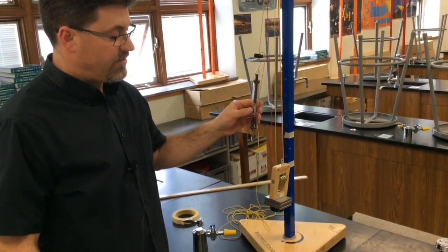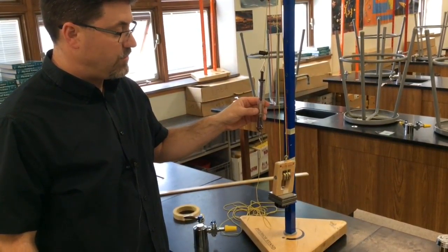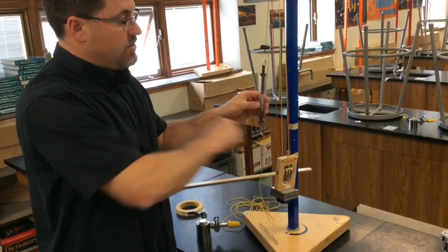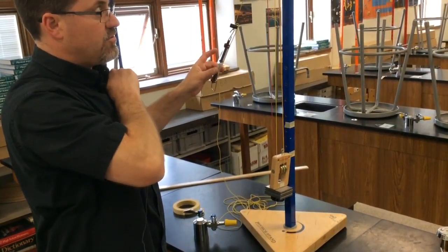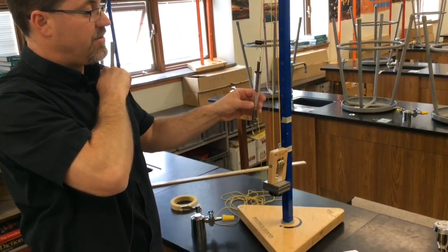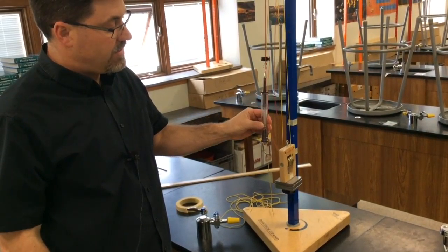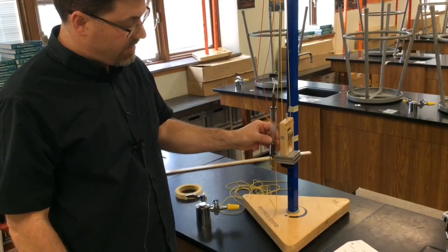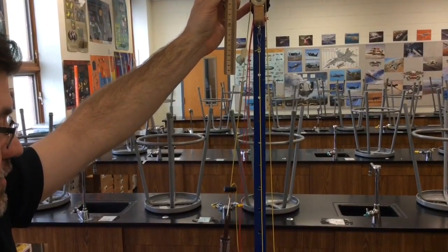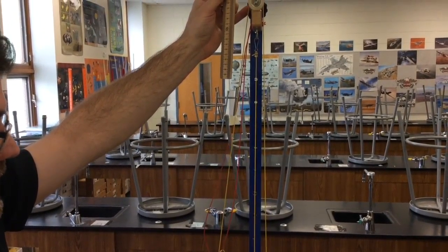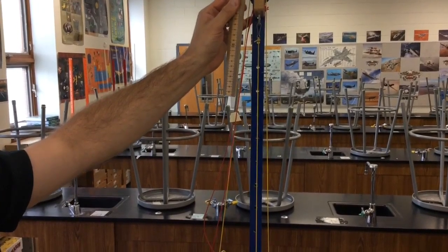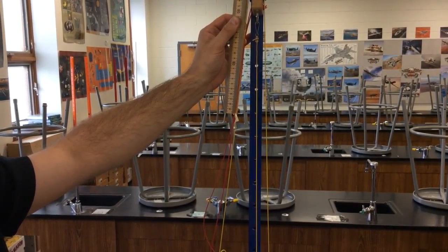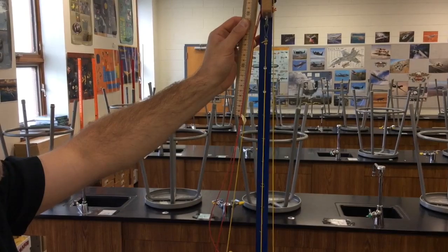For the second set of support strands, where we have 2, again, this one is not a support strand; that's what you're pulling the spring scale with. We're going to lift the block, and the force needed to lift the block is 5 newtons. You're going to pull the block up so the top of the block matches the piece of tape, and this is 20 centimeters.